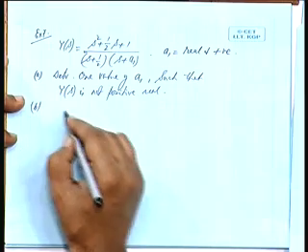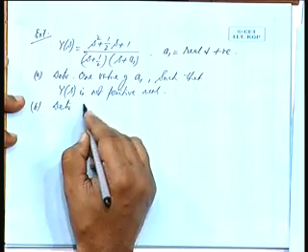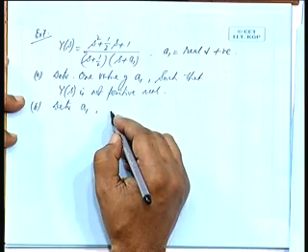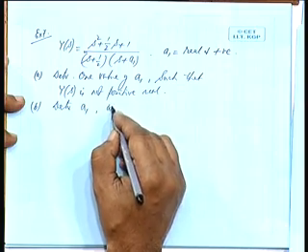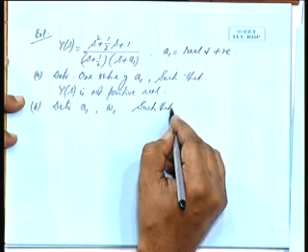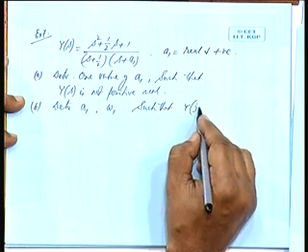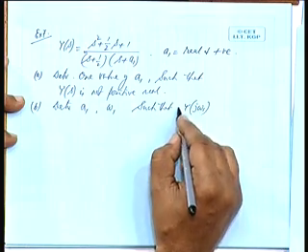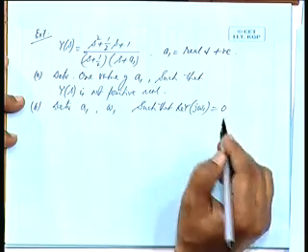Second condition is, determine A1 and also the frequency omega 1 such that at that frequency, Y(j omega 1), the real part of this is equal to 0.